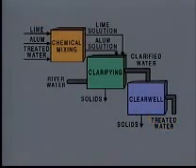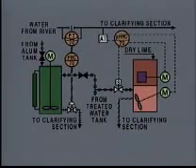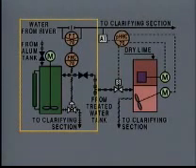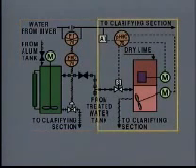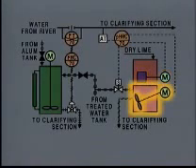Now that we've seen how the three sections of the water treatment system are connected, let's look at the P&IDs for each section. We'll start with the chemical mixing. The chemical mixing section is actually made up of two separate chemical systems, an alum system and a lime system. Let's look at the lime system first. The equipment in the lime system includes a dry lime hopper, a motor-driven shaker, and a mix tank and mixer.